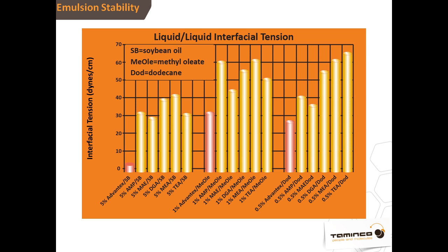Now, one question that we get commonly about using higher molecular weight, more structurally complicated amines is that they are going to be more slowly evaporating. So isn't there an issue with leaving a water-soluble amine in a coating longer? Isn't that going to degrade the water resistance?